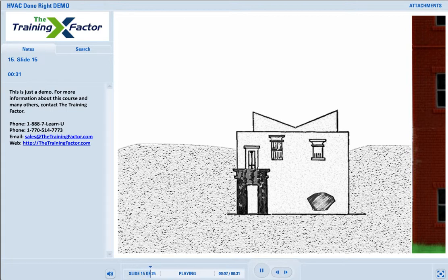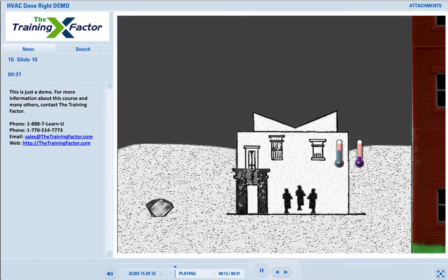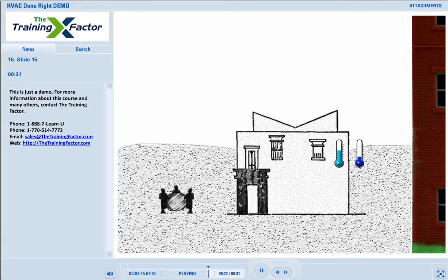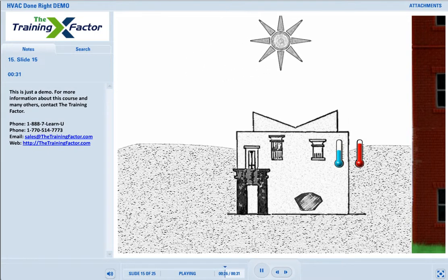In ancient times, workers would take large stone blocks out of the palace walls and homes to the desert. During the cool nights in the desert, the large stones would cool. In the morning, the workers would bring the large stones back and reset them in the wall. Hence, as the interior heated up during the day, the heat would be absorbed by the cool stones, lowering temperature inside the palace or home.